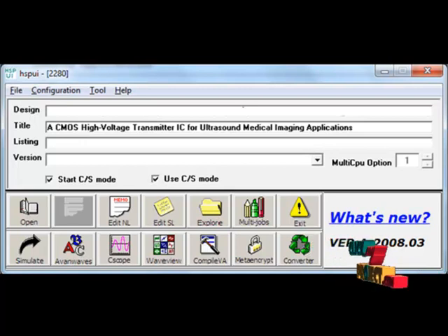Once the simulation is over, we can view the internal coding by clicking this. These are the connection details provided in the SP file format. Since in HSPICE we can't view the schematic diagrams or any other circuit diagrams, this is provided only by the coding implemented in it. After that, press the add-ons tab. This will generate the graphical representations of the output signal.